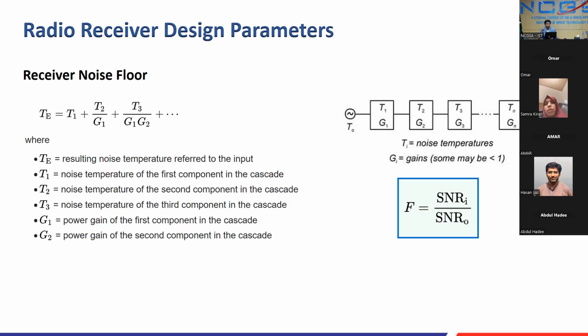above 13 dB. So that was a huge difference, because during the design or prototyping process, he did consider the noise figure, but he didn't consider how we would remove the heat from the LNAs. So the whole assembly's temperature will rise with the DC current flowing. So you also need to think about the mechanical aspect when you're designing a system, its DC contribution towards the degradation in temperature as well. So that's one example.